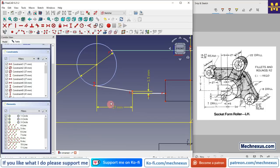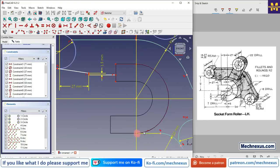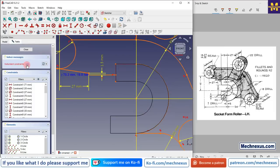And now we will create a 3-point arc exactly to this projected edge. Sometimes FreeCAD solver gives lots of errors, so we will keep the patience, and we will delete it and we will give it equal.